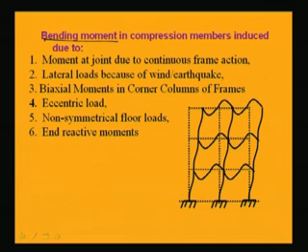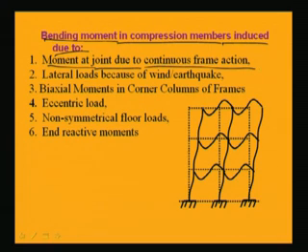Bending moment in compression members is induced due to, one, moment at joint due to continuous frame action. Another is lateral loads because of wind and earthquake.